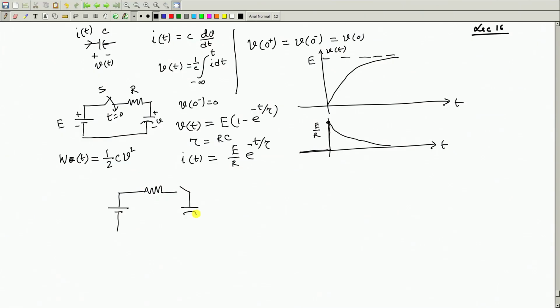This was the capacitor, and here you want to retrieve the energy stored in the capacitor in a load resistance R. This is plus minus E. When the switch was in the neutral position, neither connected to A nor B, I will presume V(0 minus) was 0 earlier, but if you close it here, then the capacitor will finally charge to the voltage E, if you wait sufficiently long.